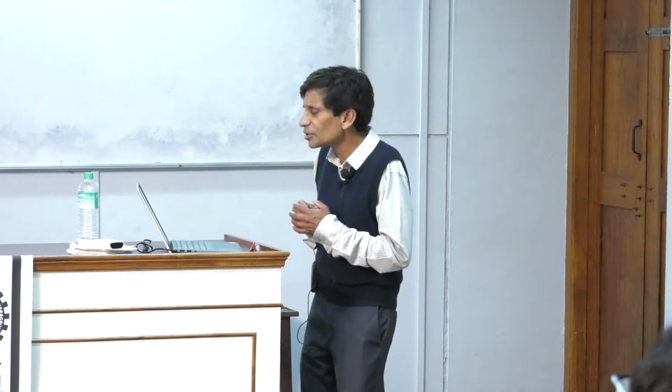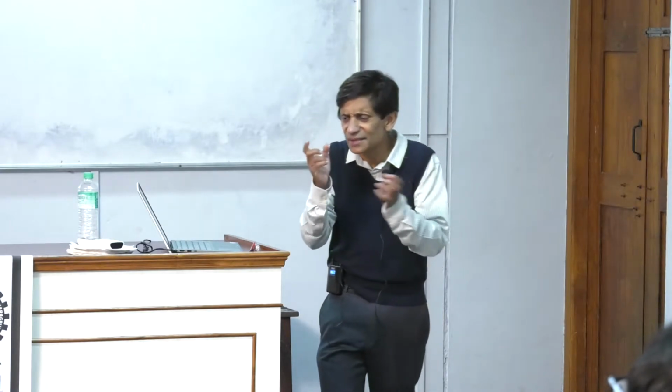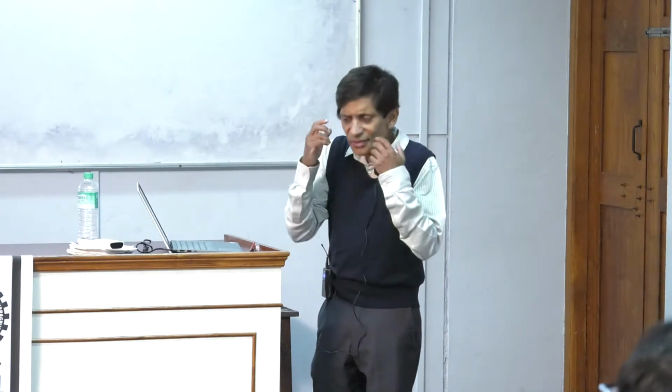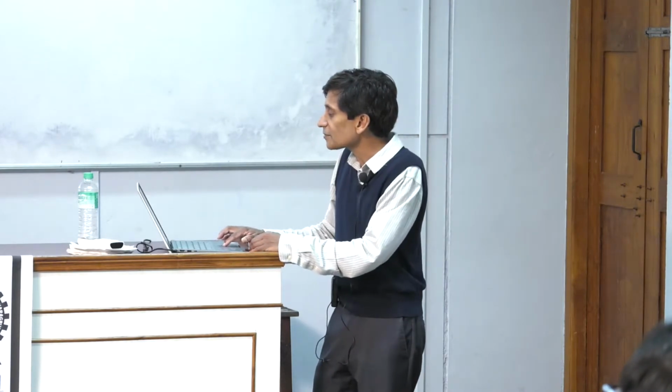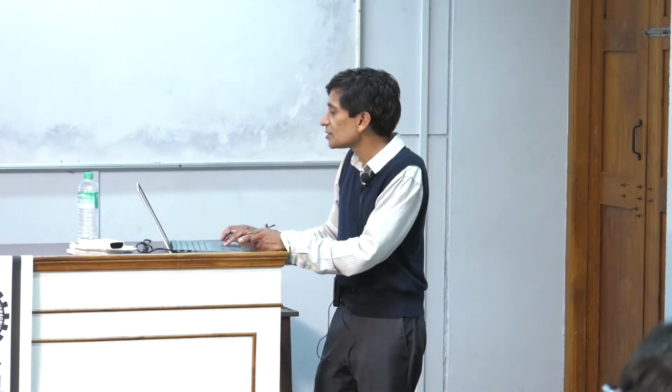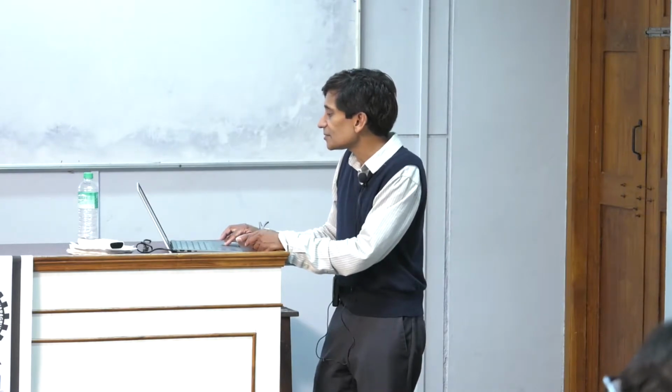When you say 0.1, 0.2, these are not absolute values. This just gives you an idea of what it is. In reality, you have to test it for your feed stream. 0.2 micron filters here are based on the removal of 10 to the 7 colony forming units.